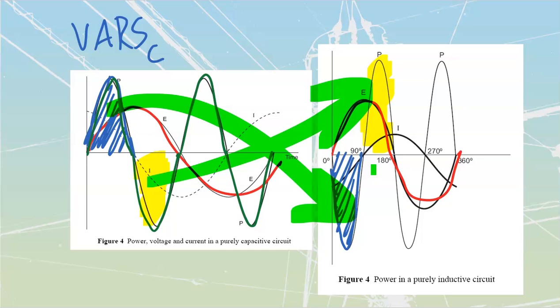Last of all, we're just going to talk about this reactive power that they have. They give us a formula for reactive power: volts times amps times the sine of theta. Sine is always going to be my opposite over top of my hypotenuse. So for most triangles, if this was going to be my theta, this would be my hypotenuse over here, and this is my opposite side over here. The opposite side is where I'm always going to have my X's. XLs, XCs are always on that far side of the triangle. The hypotenuse is going to be my impedance. We use the sine of my angle over here to figure out what I have got.